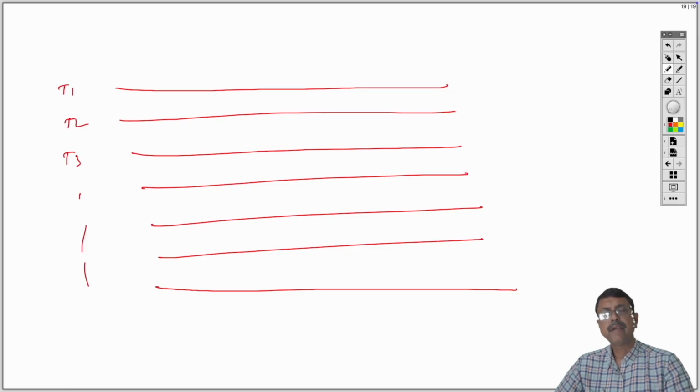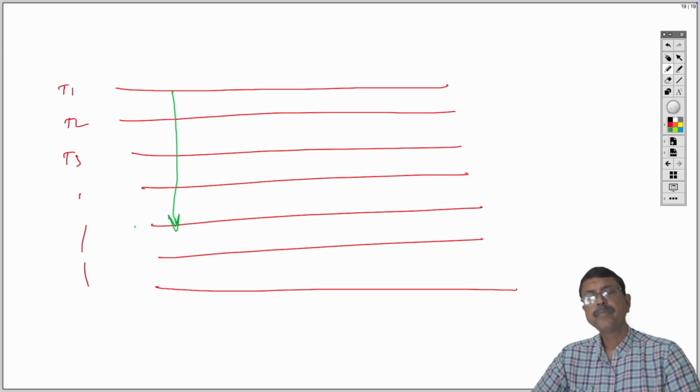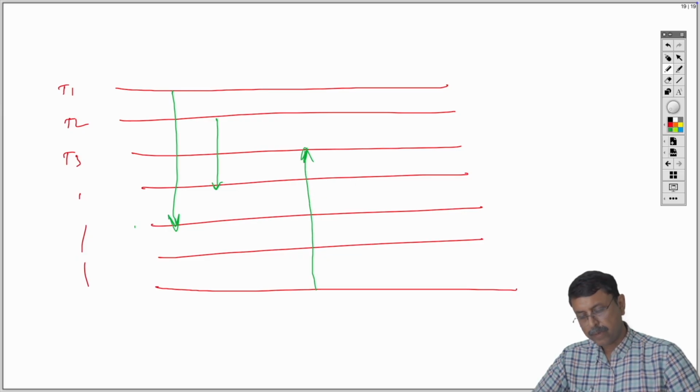And you have to identify the heat streams. So suppose the H1 is decreasing from the T1 to T5. So you will have this kind of line. Okay, H2 may be another heat stream whose temperature reduces from this point to this point. Okay, cold stream C1, this temperature rises from this point to this point.